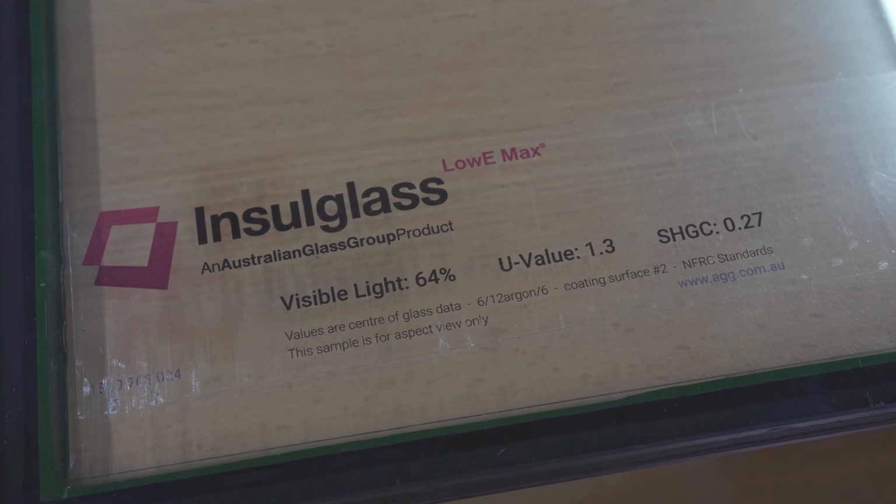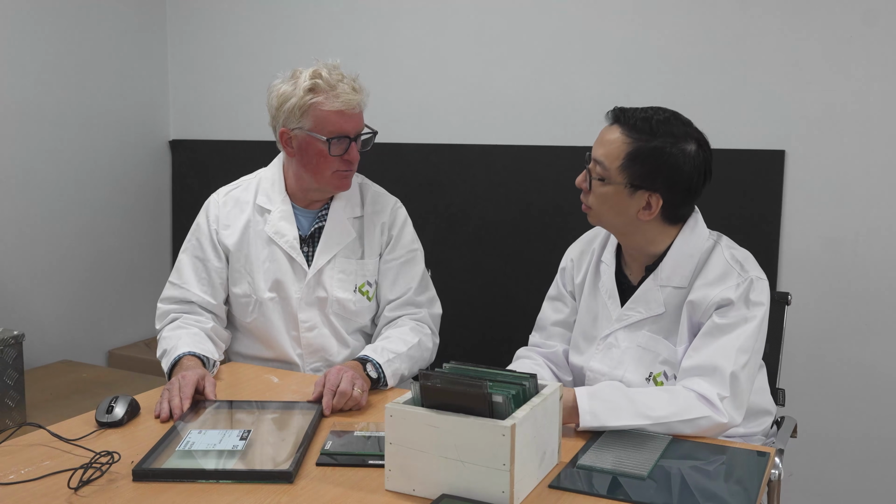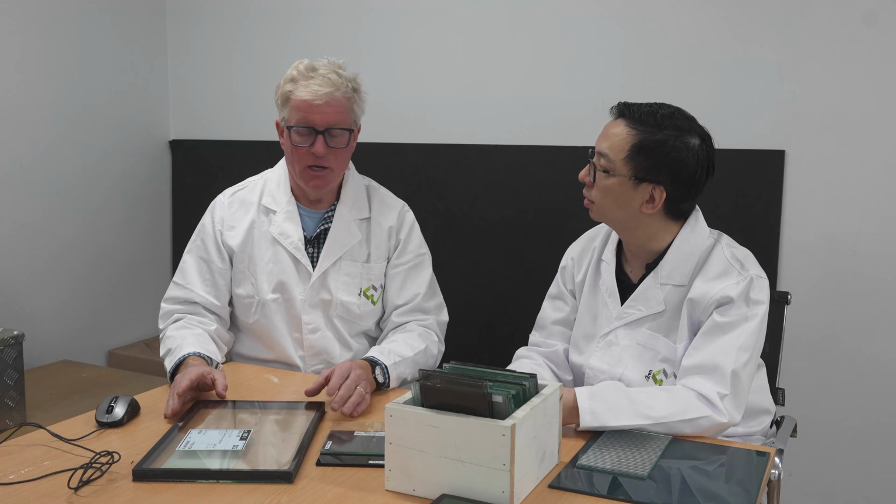Some of the advertisements claim a low E coating can help control solar gain. Is it true? A low E coating may have some mirror characteristics, very little. Mainly, a low E coating has nothing to do with the overall solar transmittance of the glass itself. What the low E does is it provides a property of low emittance. What does low emittance mean?